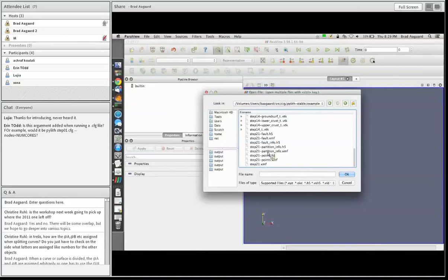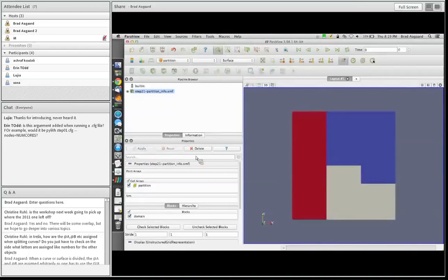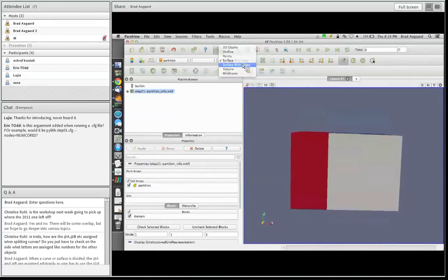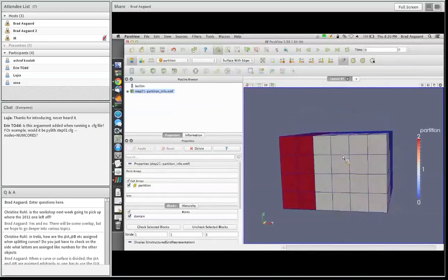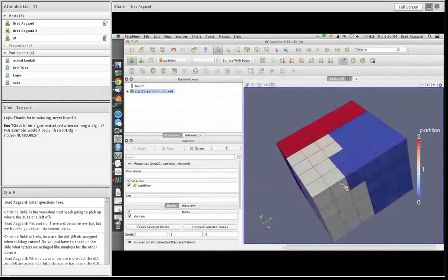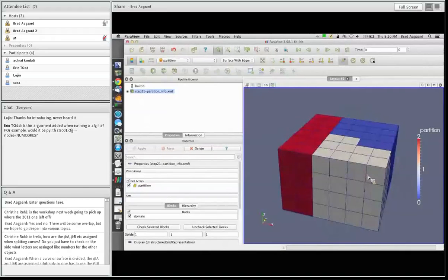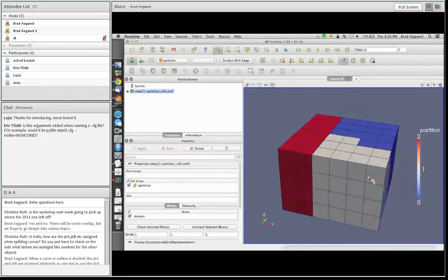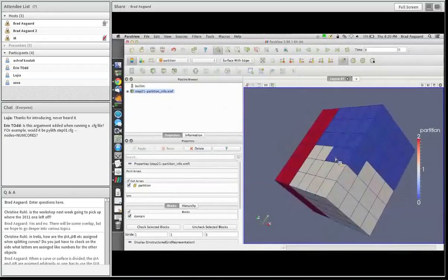So there's this partitioning profile. It has 1 value in there, partition. And so here's my partition among 3 processes. This is a pretty simple discretization. You'll notice that by doing an odd number of processes with a nice square rectangular cube that's very regular, you're going to get some irregular boundaries. So you'll see a little bit of irregularity here, whereas here it's a nice clean sweep.